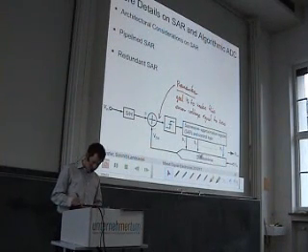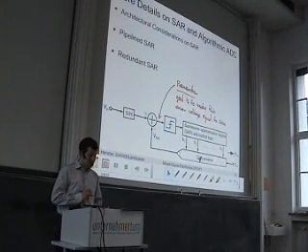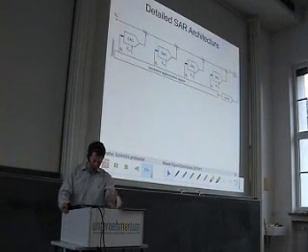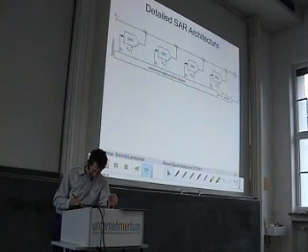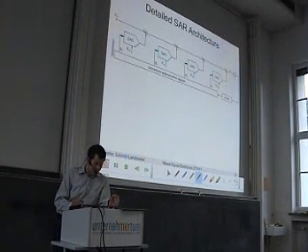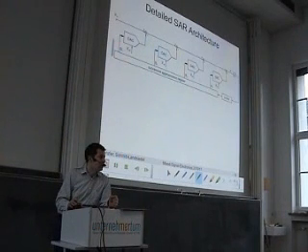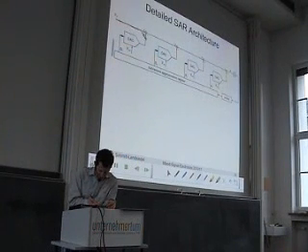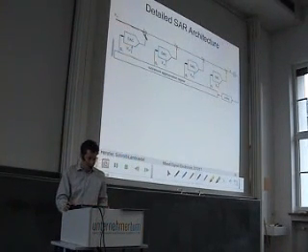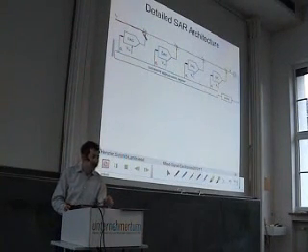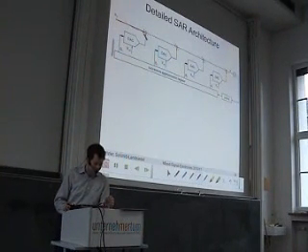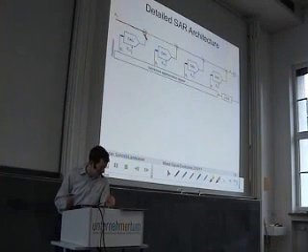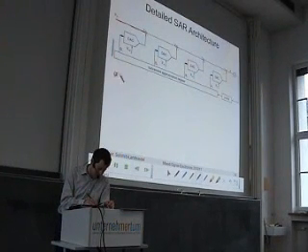Let's partition the DAC here and look into the details of this DAC. And then we might end up with an architecture like this. This is exactly the same, only that we look into the DAC. You can see here we have the input voltage, and the DAC is now separated in several sub-DACs, and you can see that these sub-DACs are all the same. Same reference voltage, same DAC. So we have here a thermometer coding.